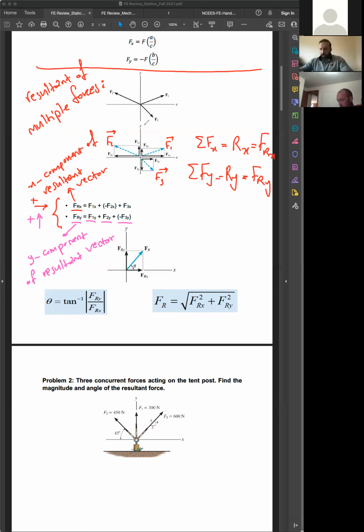So when you find a resultant vector, it is only one vector as a result of everything. So that FR really can be expressed as FRX and FRY. So you have a new vector. Instead of all the vectors in the system, you only have one vector. Okay. So this is what you see here. You have the resultant vector FR. It has an X component. It has a Y component, right? As you have found here and here.